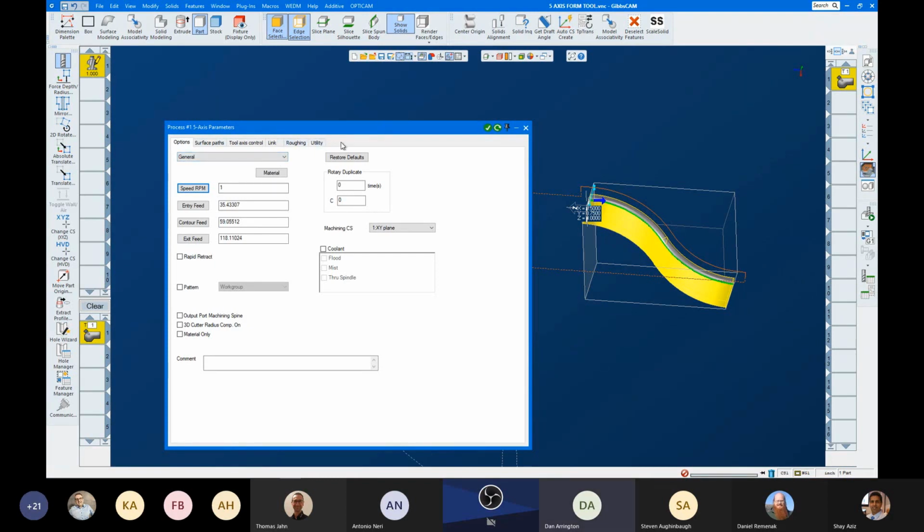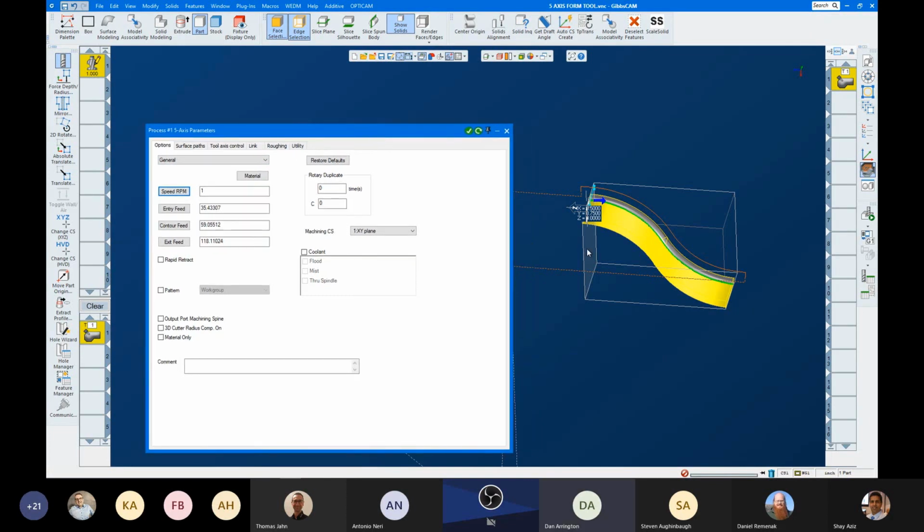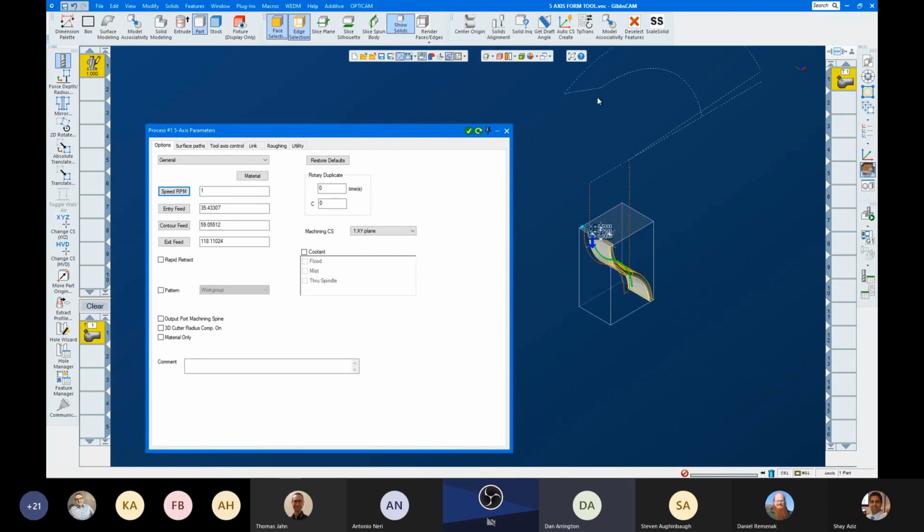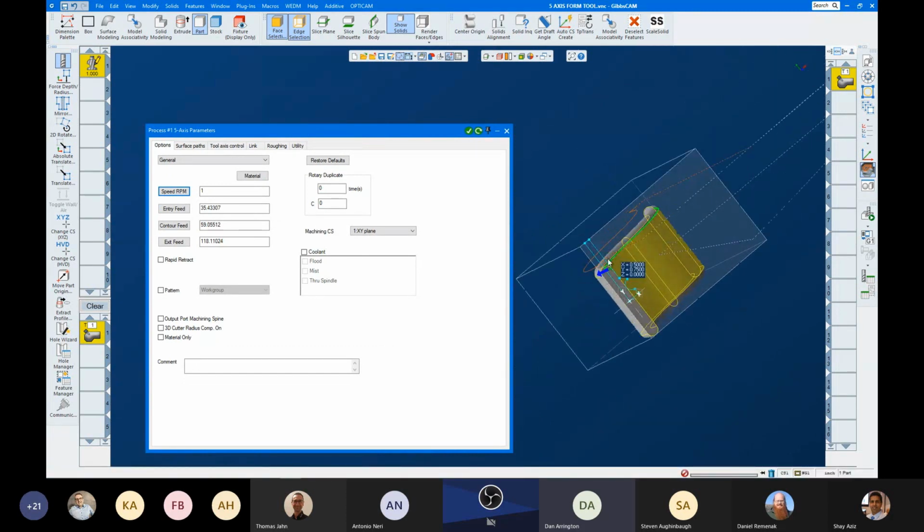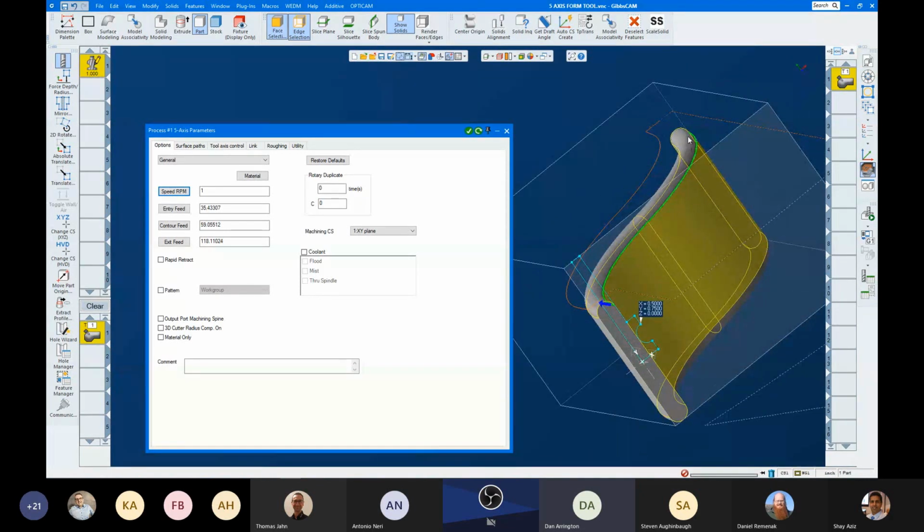And the reason for that is there's a lot going on. And honestly, if you're using a tool like this, what we're going to do is round over this side here. You're probably gouging just because of the nature of the shape of the tool, the clearances that the tool has, and the shape of the surface that you're trying to create or produce.